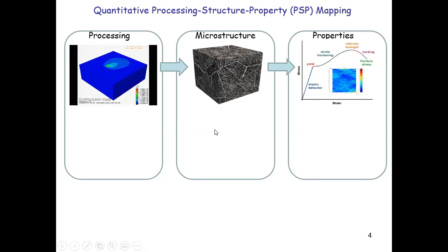And during this process, after you make the material together, because you heat up the material in a certain way, either make it into liquid or just heat up and then cool it down, right? So this means that the material can undergo a different type of thermal cycle, and this will typically introduce a phase transformation in the material. Like in this laser sintering process, initially you start with a material with very large grains, like these. This is the microstructure after laser sintering, but before the sintering, you do not see these very fine beta grains in these directions.